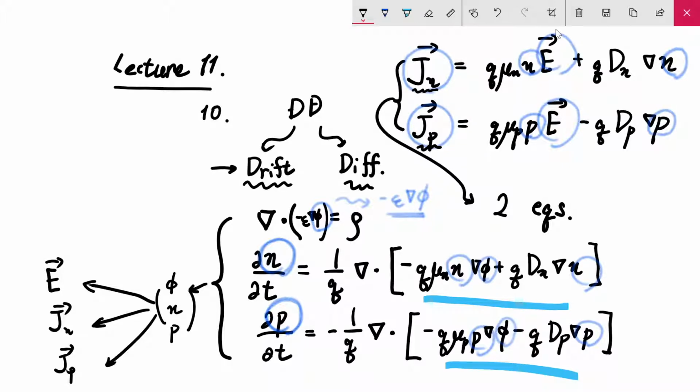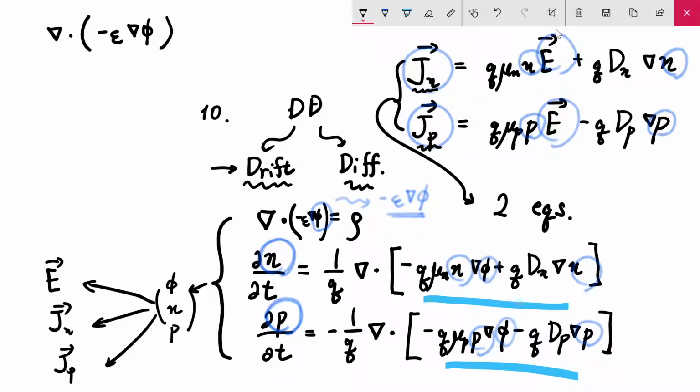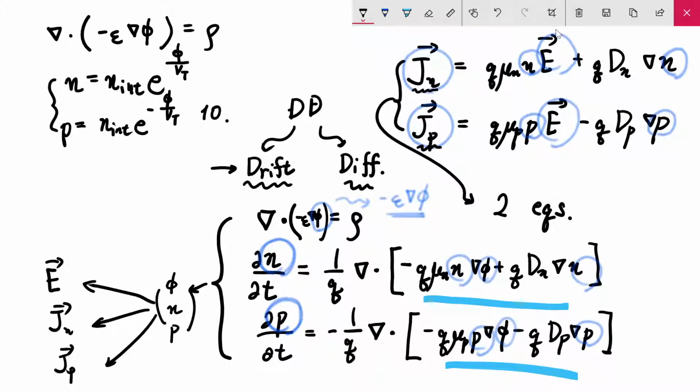Yes, sure. So this is the general drift diffusion model, and in our homework number 10, instead of this general one, we have introduced a system which is strictly valid at equilibrium, only at equilibrium. So you may remember this is the equation at hand, and p is given by n i squared over n. These expressions are valid at equilibrium, and also we have an additional approximation. In order to have such an expression, we have to adopt the Boltzmann statistics. So you know that. So we have two different statistics appearing in this field.